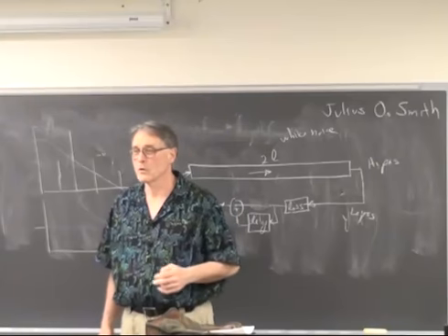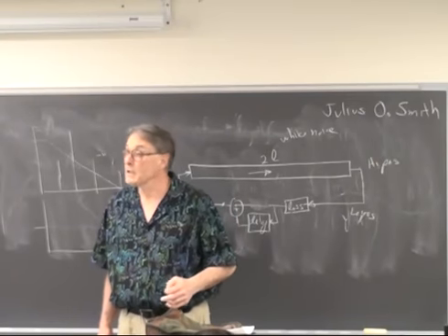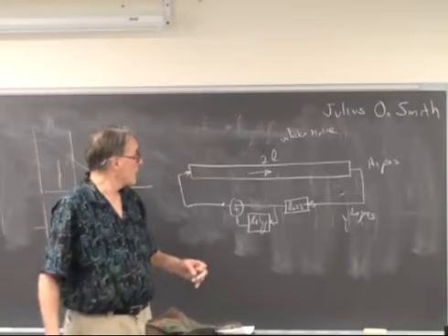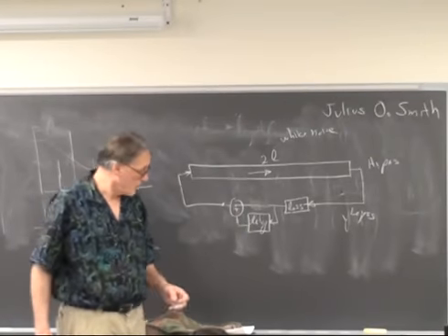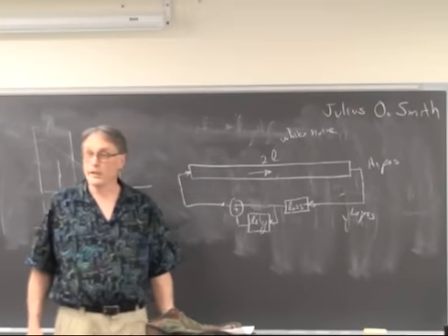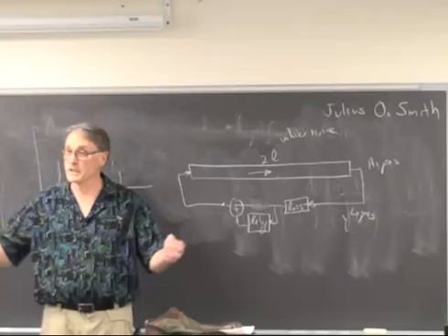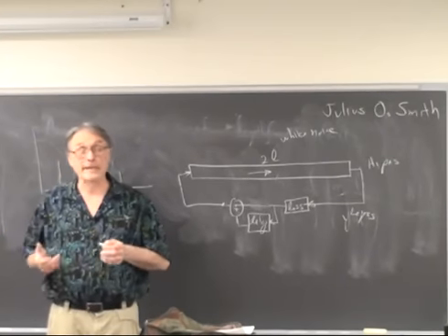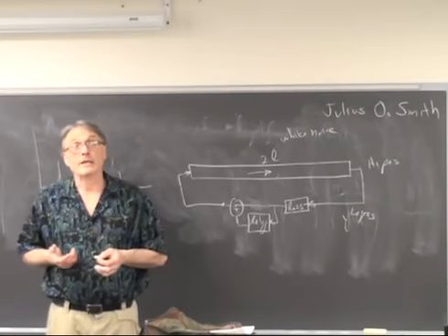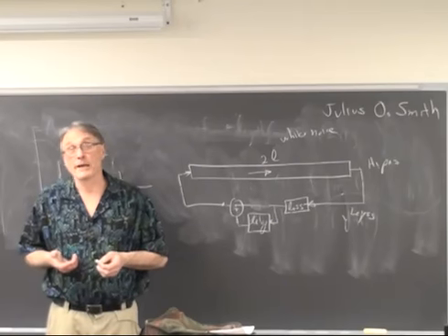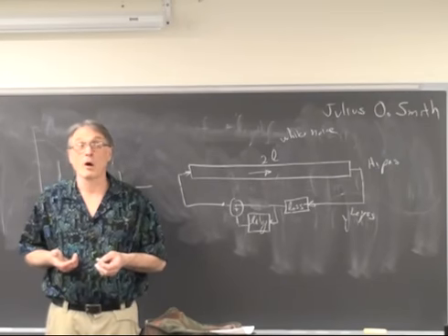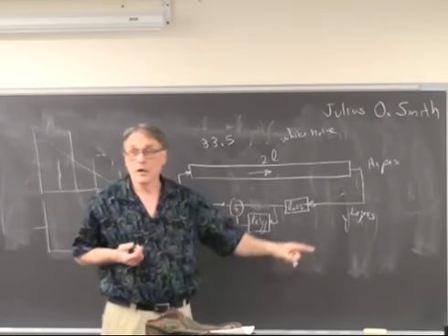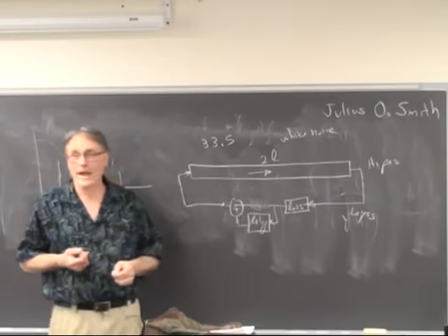How will we determine the length of air? Say again? How will we determine the length of air? Oh, the length. Well, you tune it. The longer it is, the lower the pitch, because the longer it takes circulating. So you can calculate that at an 8 kilohertz sample rate, middle C is going to require a shift register of length 33 and a half.